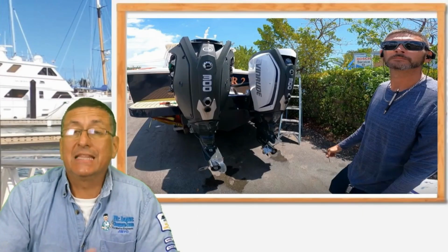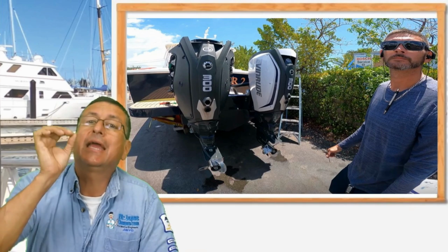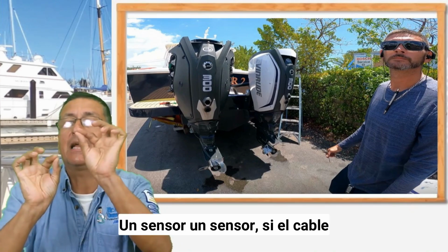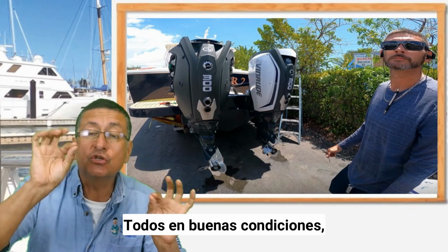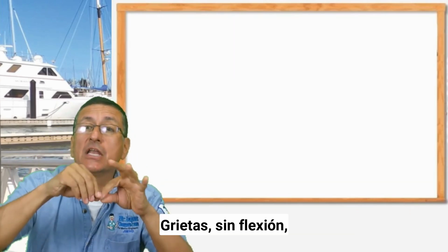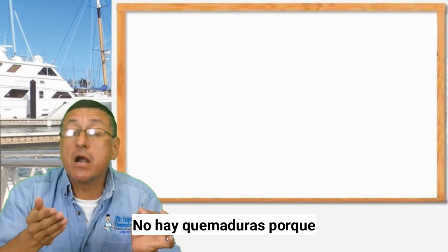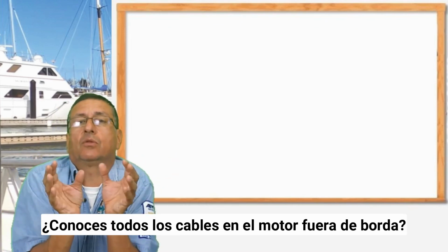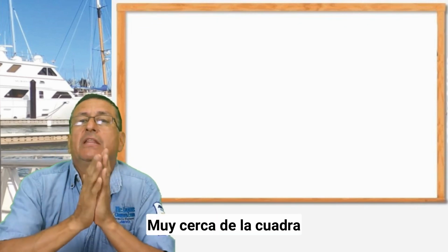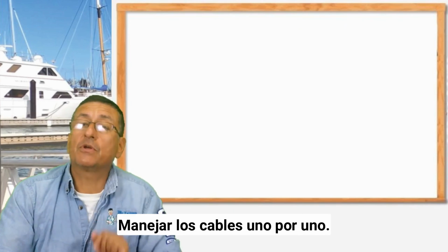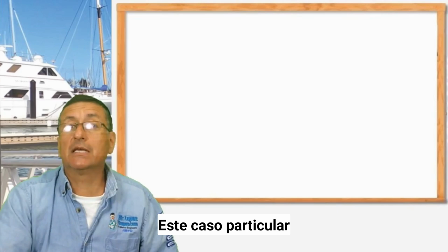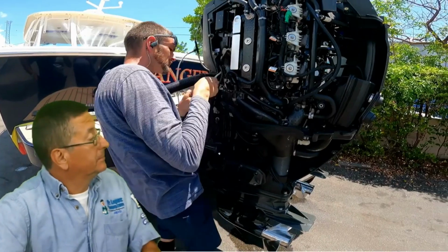And now Danny starts to check cable by cable, sensor by sensor, to see if the cables are in good condition: no cracks, no bends, no burns, because in outboards all the cables are together, enclosed and pretty close to the block of the engine. It's a long process, in this case more than 2 hours.